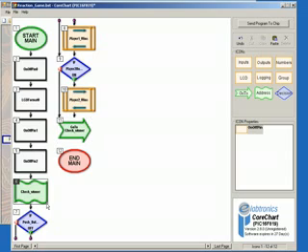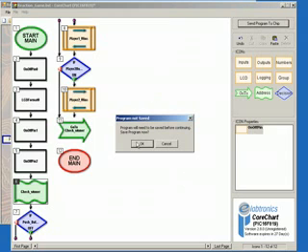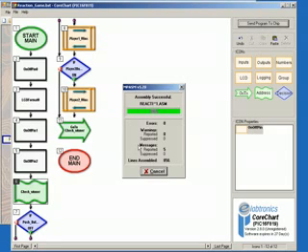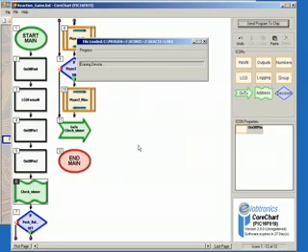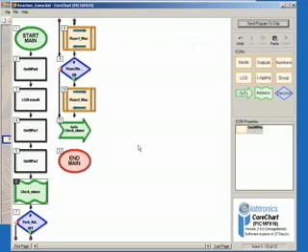To run this, make sure that the hardware is connected correctly, and then again, simply click on the Send Program to Chip button, and then OK when prompted to save. Once the program is completed being downloaded to the chip, to start the program, simply push the push button switch on the controller board, and then once the buzzer stops and the yellow LED turns on, the first person to push their button wins. This concludes Project 3.